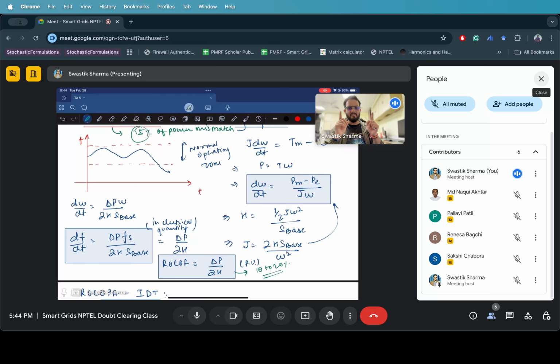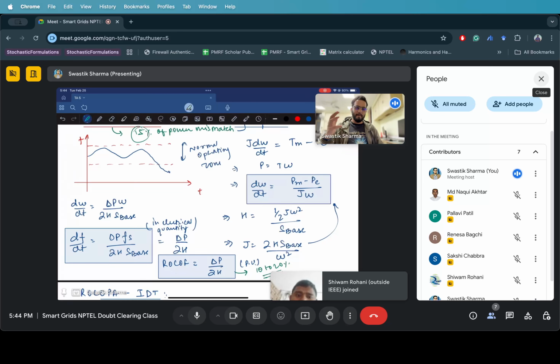So this acts like a virtual inertia. We always do that when we have only inverter based DRs present in our microgrid. We'll discuss more on how inertia and droop control are implemented for purely inverter based DRs in the system. But that is how it's done. We have some virtual inertia in our systems to provide the headroom for us to navigate between different varying frequency levels.